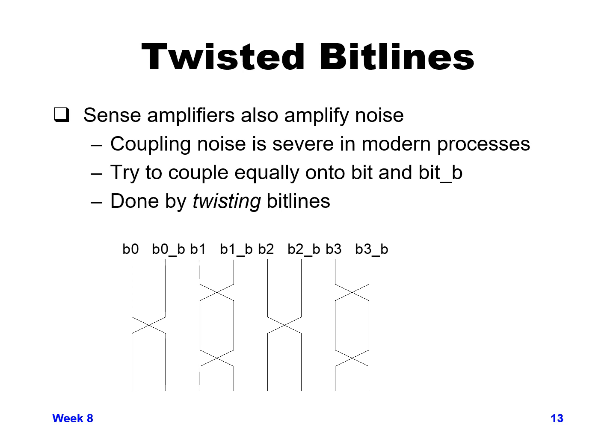So if you have, for example, your bit lines going to be vertically driven, and bit 1 and bit 1 bar are going to be pretty close. Bit 0 is close to bit 1. And so if you have, let's say, bit 1 is trying to pull down, but bit 0 bar is trying to stay high, bit 1 will couple onto bit 0 bar, and we don't want that.